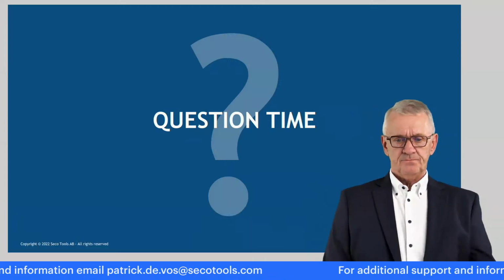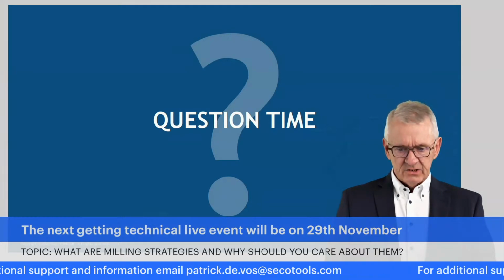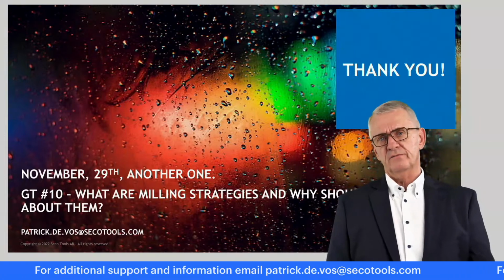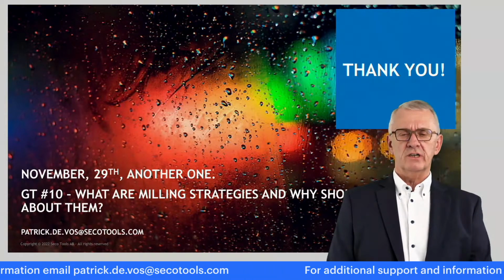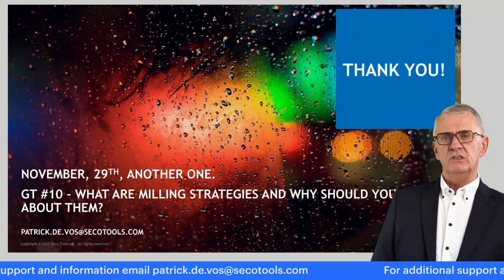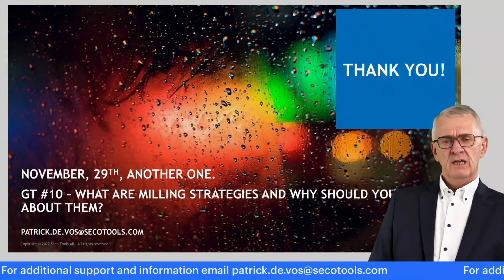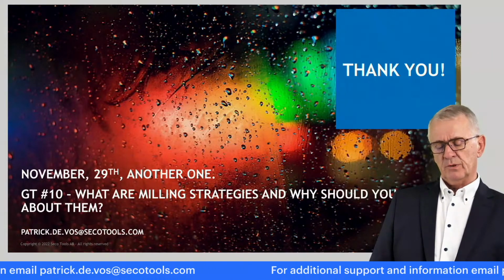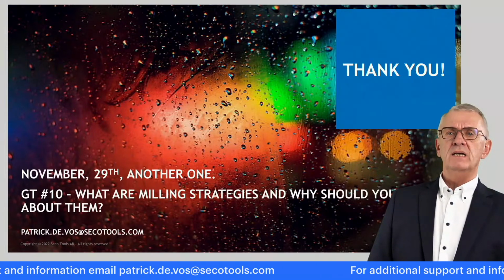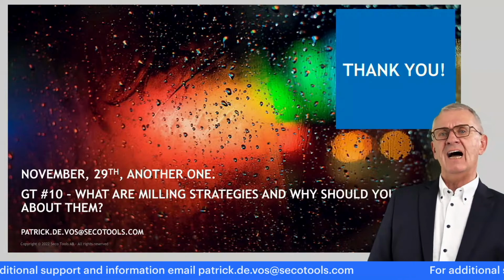Having said that, that means we are at the end of this session. Again, I hope on behalf of my colleagues and myself that we spent an interesting hour together, that we elaborated a bit on economic machining, one of the scenarios defined in machining economics. A bit confusing words here, but that's how it is. We focus on cost, we focus on time, and we ask ourselves the question, how can we set up a machining process? How can we select a strategy? How can we select a tool? How can we select cutting conditions so we minimize the costs related to the machining process, or maximize the productivity, the output of the machining process?